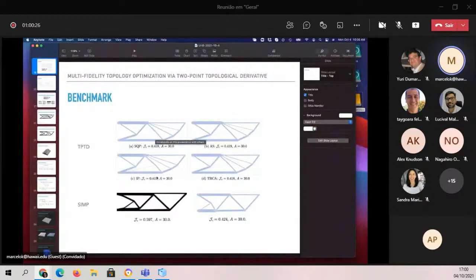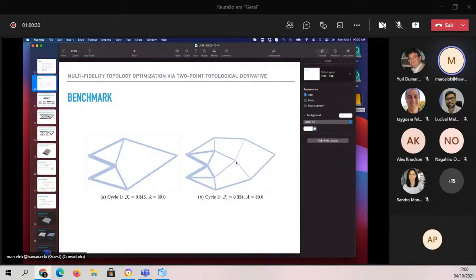And I should mention here, problems like trusses, this is not really a truss, this is a frame, because it can carry bending. But as the volume fraction is reduced, this approximates a truss. Now, there is a well-known result from Michell from 1904, where if you have a domain like this and a problem like this, and you try to put a truss on that, there is no solution. I mean, there is a solution, but not really, because that solution has an infinite number of members.